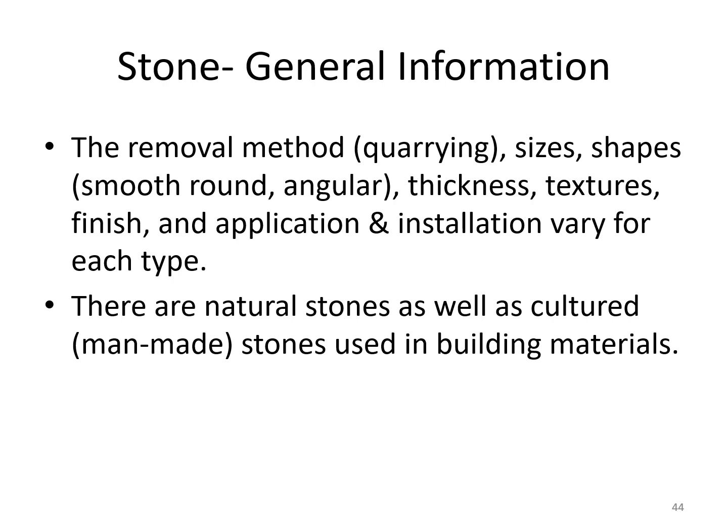So stone, the general removal method, of course, is quarrying. If you ever watched how they do this in quarries, it's pretty impressive. Taking out giant chunks of stone, even the granite and so on and so forth. They're cut through with giant metal diamond blade saws. They come out in blocks that maybe weigh 20, 30 tons. They're like 15, 20 feet by 10 feet by 10 feet cubes. And then they're cut into thin layers. I call it a bread cutting machine. It takes a couple days to cut through them, and you end up with a marble for your countertop, maybe being an inch and a half thick.